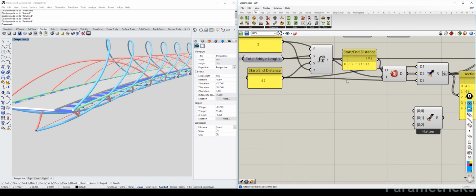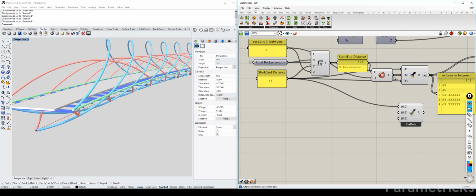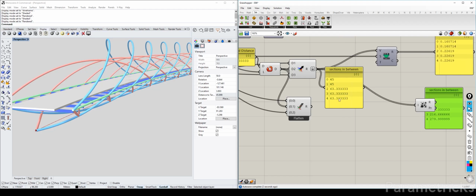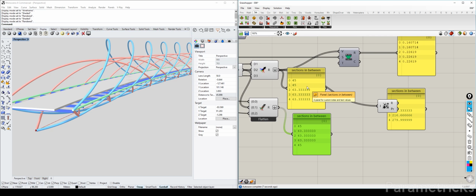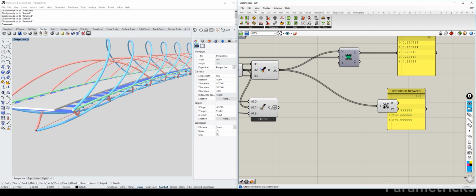If you were to do the same with an entwine and then flatten that entwine, you will see the difference in the ordering of points that it kept. So I'm going to go here and flatten the entwine. You see the ordering is exactly how I expect it to be, but the merge actually pre-sorted our numerical values, which I don't want in this case.